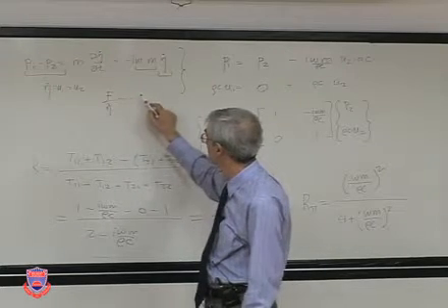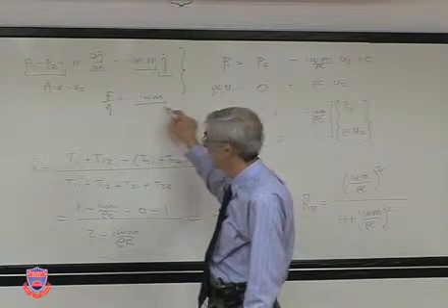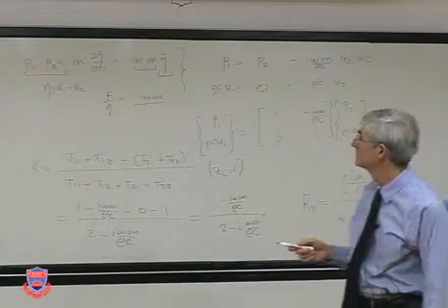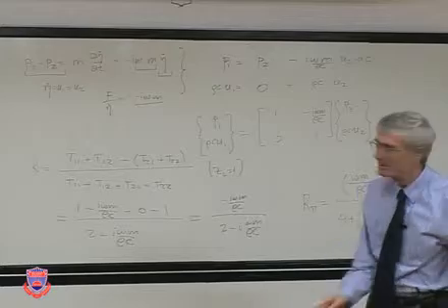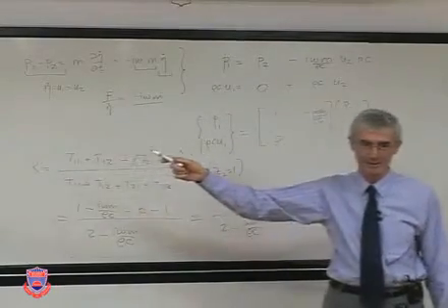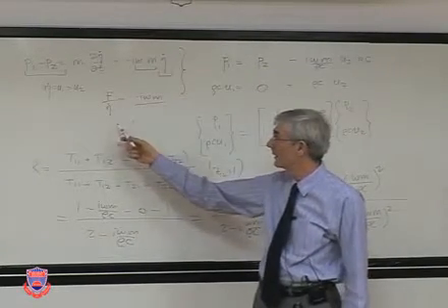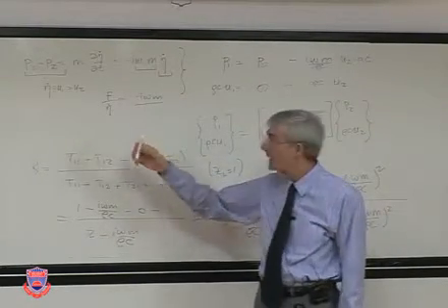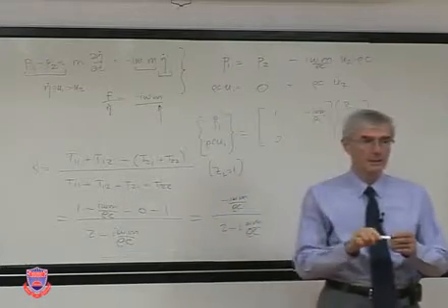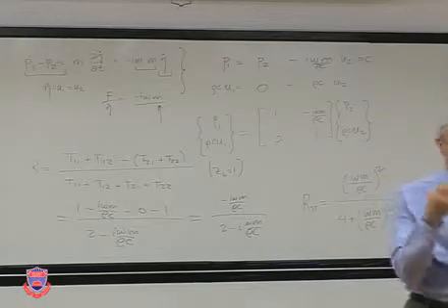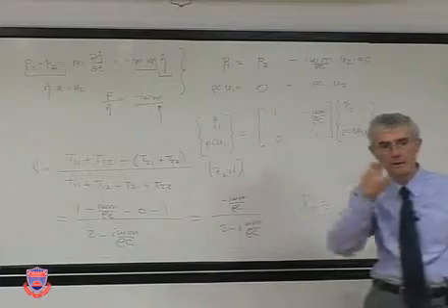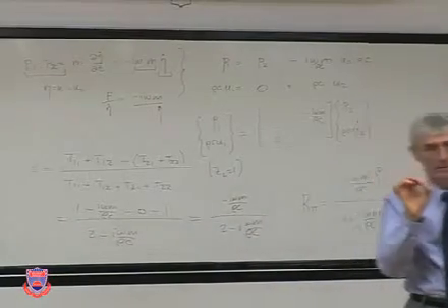What would this be? Impedance. Force divided by velocity. Remember, the membrane does not have stiffness. Force divided by velocity is impedance. And what kind of impedance? This is called inertial impedance, meaning mass impedance. Every time you see i omega m, it's a mass impedance.